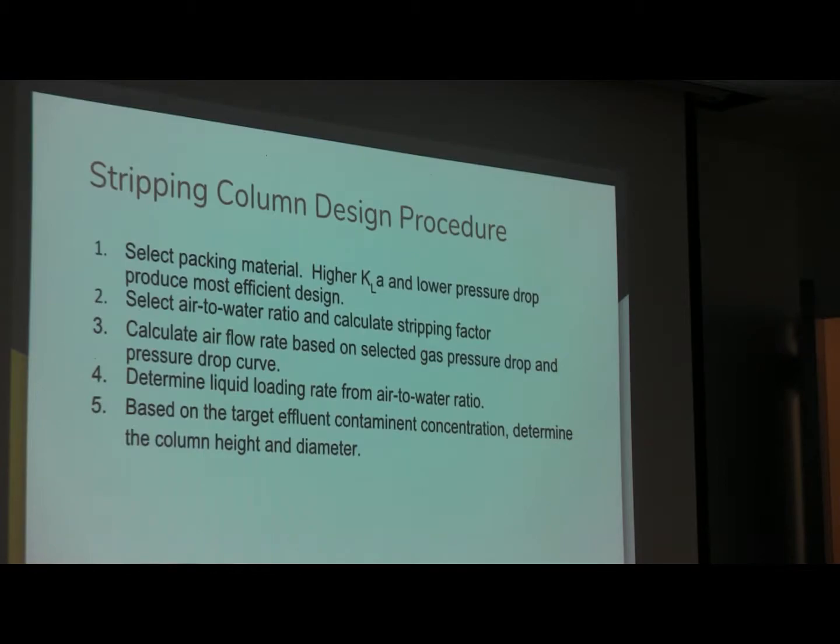And since we have the operating gas to liquid flow ratio, we can get the liquid loading, and then we use the height equation and the diameter equation to help us determine the size of the column.